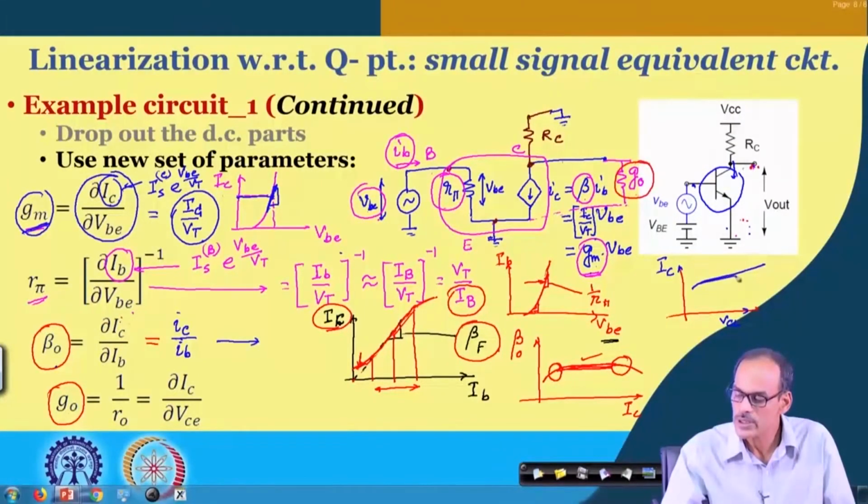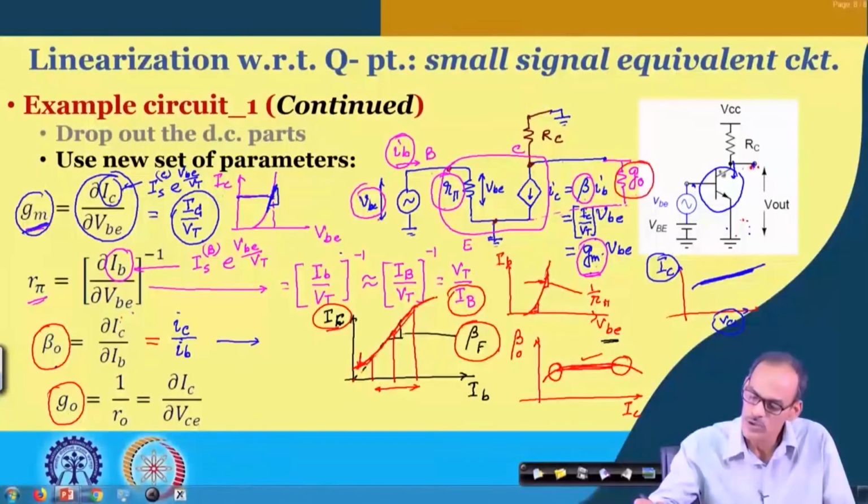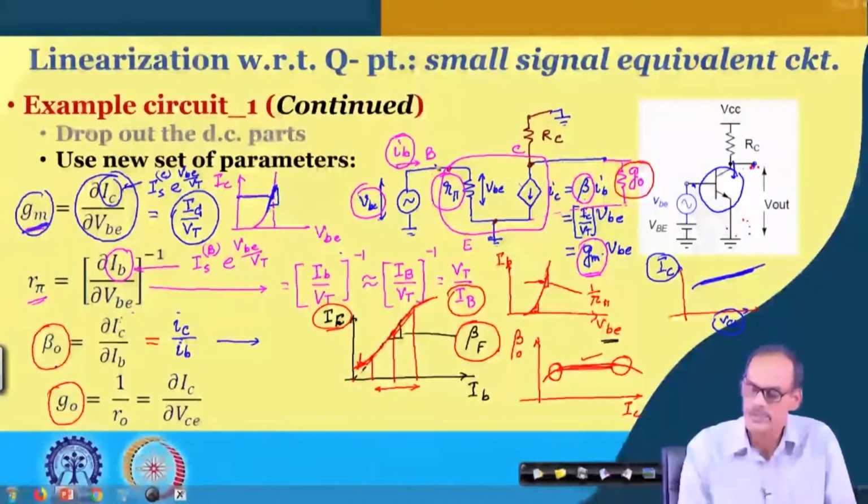In other words, if we observe the collector current while varying VCE, it increases. If I increase this voltage, the total current increases, which means the total current is not completely defined by the condition at the base; in fact, some part is also dependent on this.